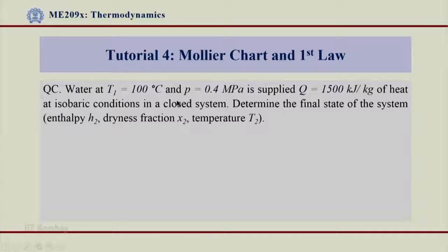Let us now again understand, we can possibly have a cylinder piston arrangement, have state 1 in that and state 2 can be found out. So, always try to draw some kind of a cylinder piston arrangement or a schematic to show the system first. Try to show your system also on a PT diagram if we are sure about the state, and that will actually clarify a lot of doubts. For understanding purposes, those things are always essential. Okay. So, let us come to question C solution now.